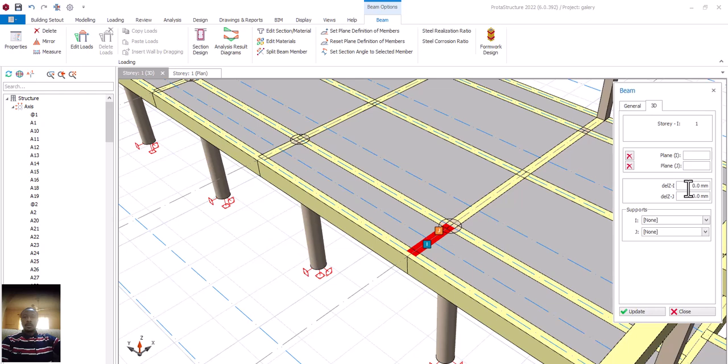At this place, top, there's Z I is going to be what? Because the top, I'm taking it down by what? By minus 600. Then click on both sides. Is that okay? On both sides. And there's J, because this side is J, while this side is I. So I'll now put minus 600 also. Minus 600 also. I'll click on update.